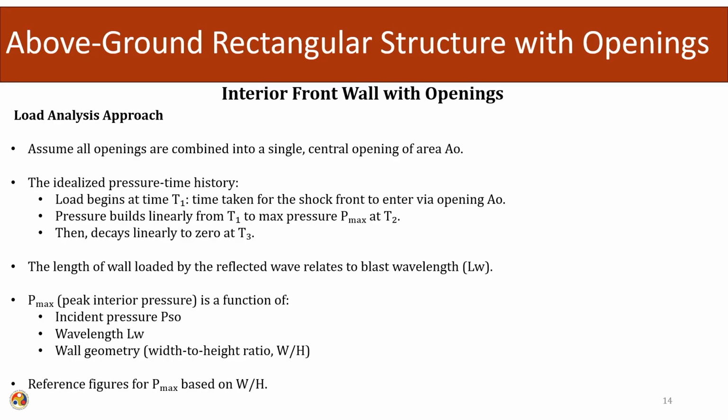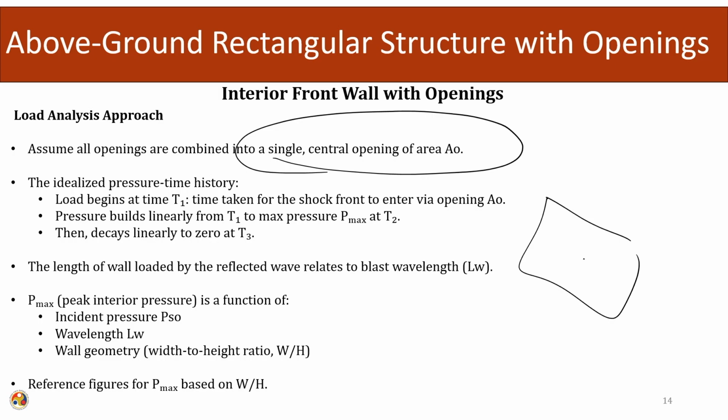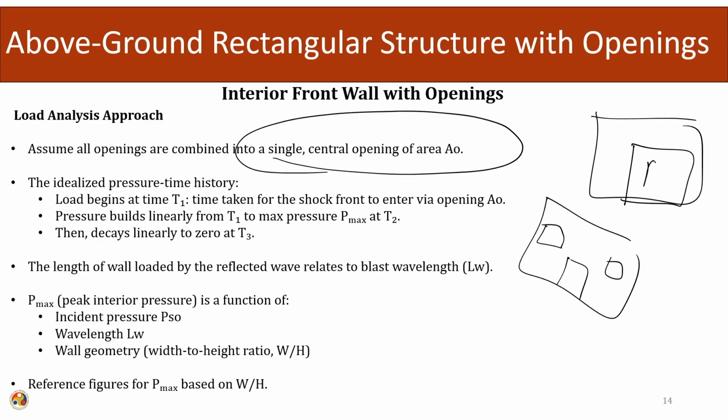So what is the load analysis approach? We assume all openings are combined into a single central opening with an equivalent area of A naught. Whatever the openings are, due to doors, windows and any other things, we combine them into a single opening area, with area A naught.